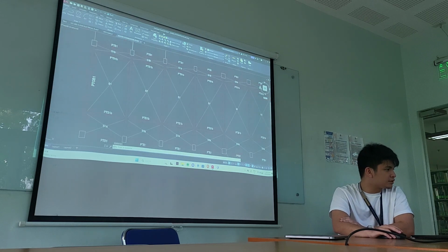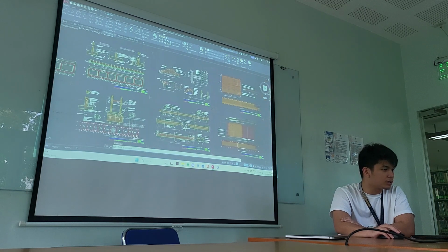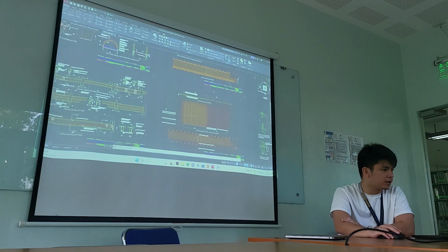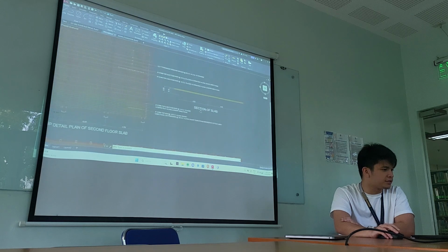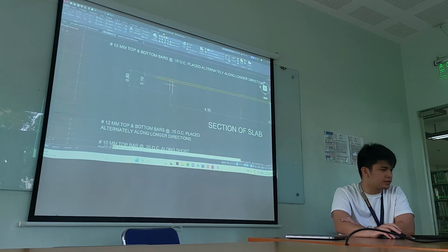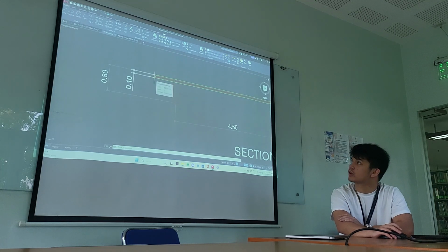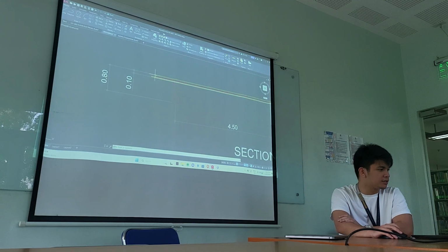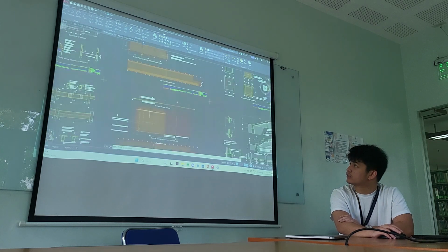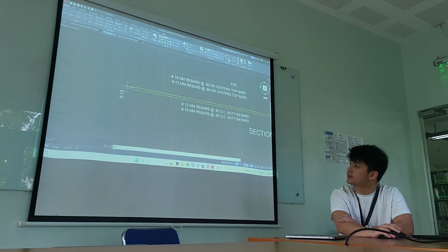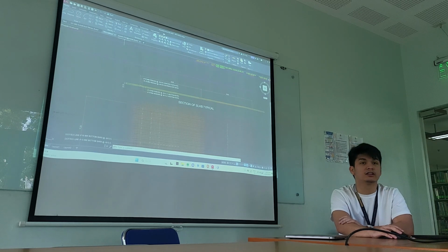for the slabs, it was found that it had a thickness of 0.13 as found in the typical slab section details here at the PPO office's file. So here, these are the columns and these are the beams, rather. So the thickness is about 0.10 for the second floor, and for the third floor it is about 0.13 meters. So that's 130 millimeters.